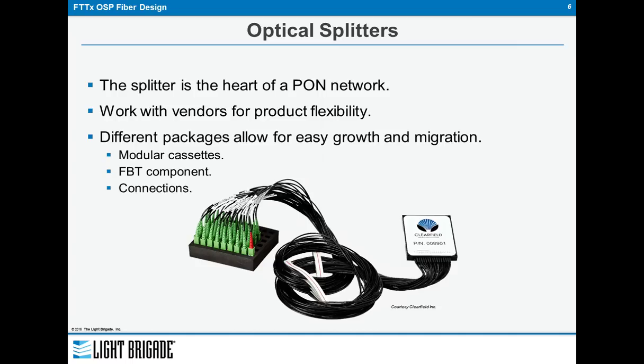There's a couple different design types. There's planar. FBT stands for fused biconic taper, which is a method by which they're manufactured. Typically those are smaller counts, but they're very small in profile. So in some cases they would only occupy one slot, similar to the space required for a heat shrink sleeve for a fusion splice on optic fiber cable.